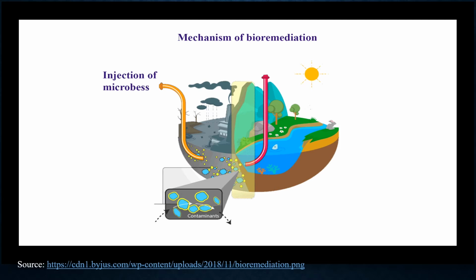Bioremediation mechanism. Microorganisms destroy organic contaminants by using the chemicals for their growth and reproduction. Waste materials are examined and certain bacteria are isolated based on their efficacy at digesting and converting the waste. Indigenous or local bacteria are to be used. The bacteria then go through several steps of cultures and processes for performance testing. The suitable bacteria are placed back in the waste environment. Bacteria will grow and thrive in the process, and then digest and convert the waste into carbon dioxide and water. The right temperature, nutrients, and food must be present, and conditions are improved by adding amendments.